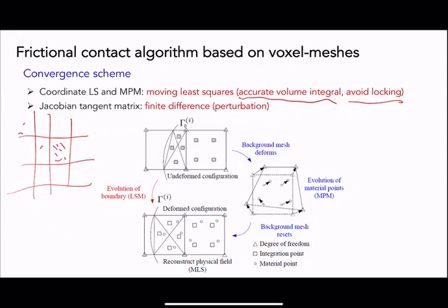So what we do is the following. We use a trick that is very common in the material point community. In the initial time step, we use the classical Gaussian point locations, or if you have a triangle element, we just put the material point in the middle to better capture the boundary. But when the material point moves, we use the new material point values and moving least squares projection to compute the corresponding values of any material property or internal variable back onto the old Gaussian points.